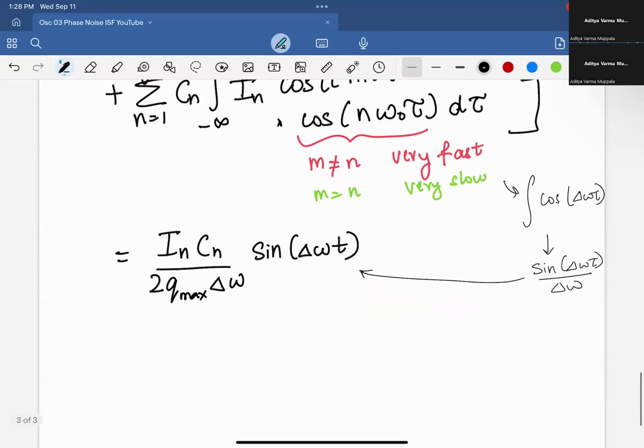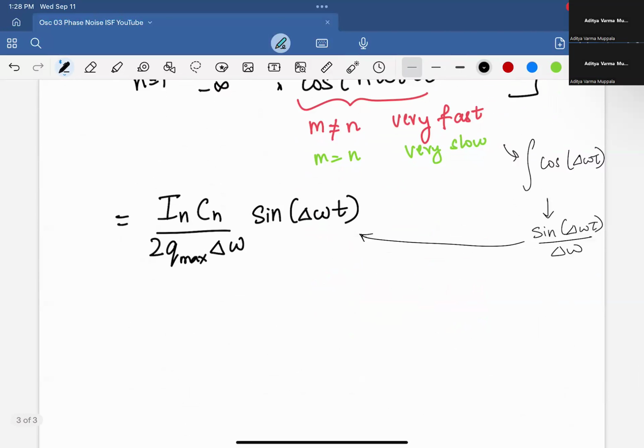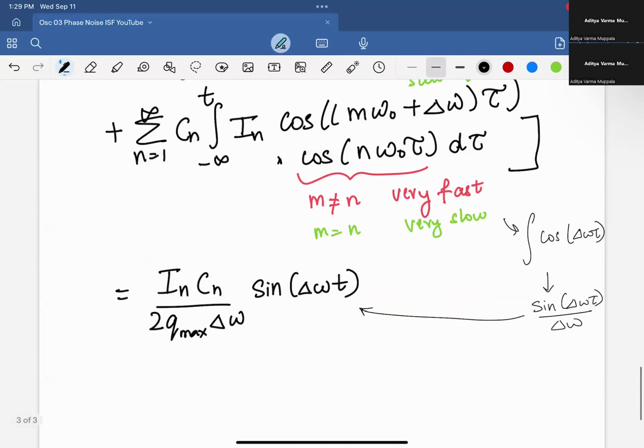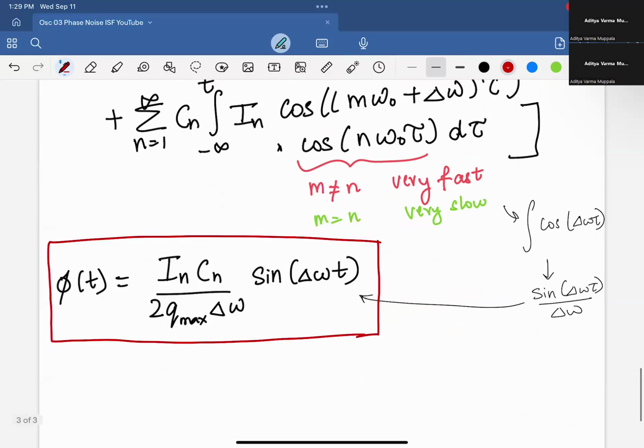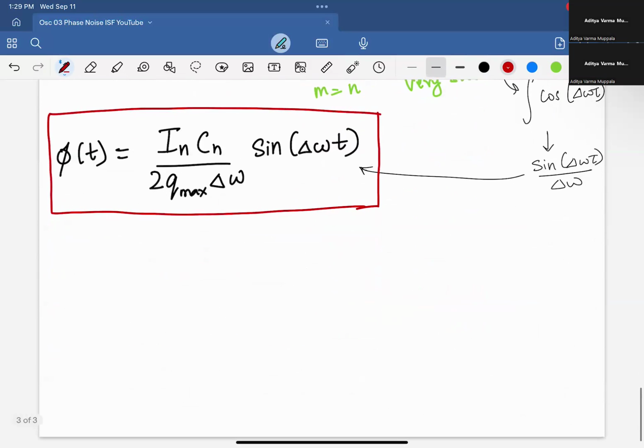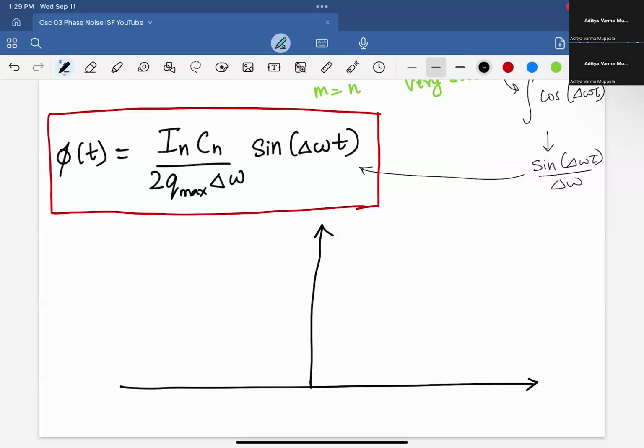Okay. So this is of course an approximation. So let's say P of t is this, and this is an important relationship, right? So what is this saying? This is saying graphically that if you plot, let's say, the power spectral density of this signal, now P of omega, then you end up with two tones, because it's a sinusoid, on both sides at a separation of delta omega.